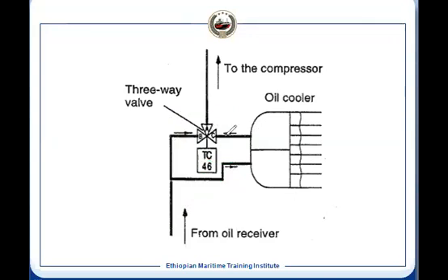So depending on the temperature to be maintained, how much will be the mixing? It's exactly the same. We mix two fluids, and then we can maintain a temperature. One will be a high temperature fluid, the same fluid we are mixing, and one will be low temperature. After mixing, it will be at some equilibrium temperature in between. Then it will go to the compressor, and we have a set value for how much it will be maintained, and accordingly the mixing proportion, how much mass will be mixed, is decided.